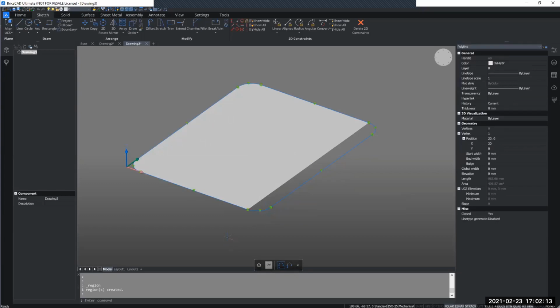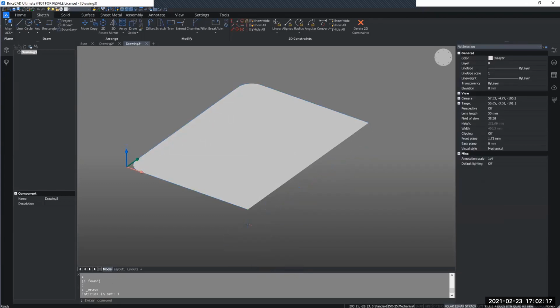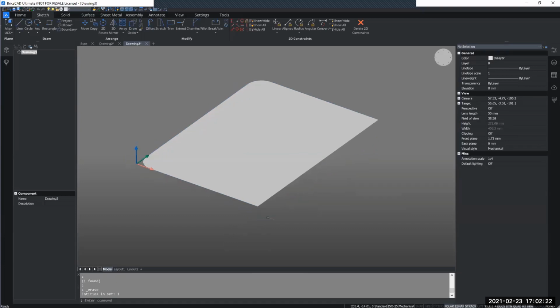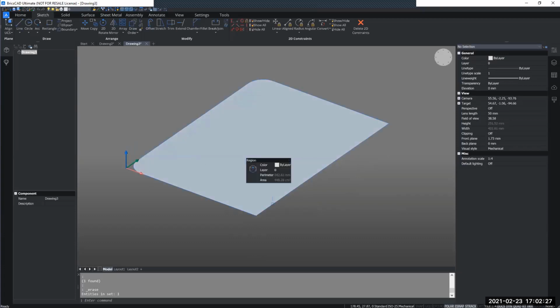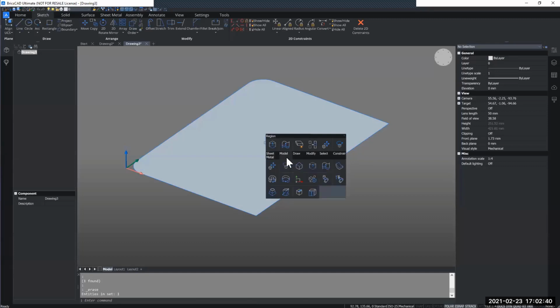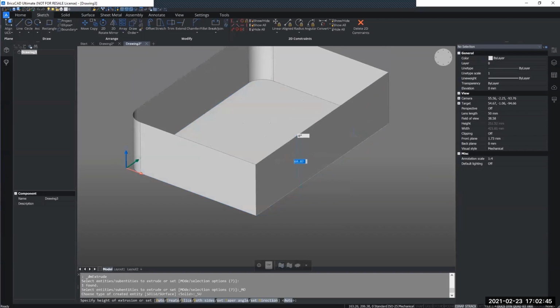The sketch will still remain, so it is not necessary to keep here for now, so I will just delete it by selecting it and hitting delete on my keyboard. Next, in step 4, I'm going to extrude the outer edges of this surface or this region. To do this, you can again use the DM extrude command with the surface mode, or you can hover over it, go to the model tab and find the surface extrude option as such.